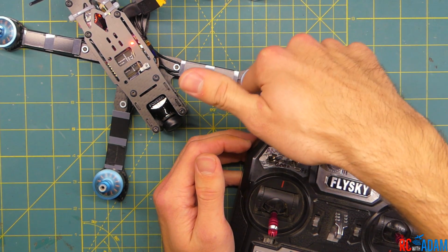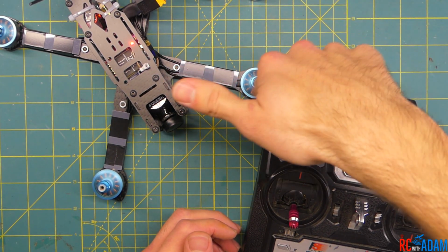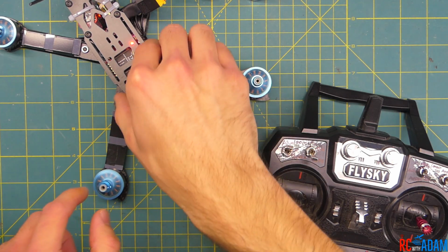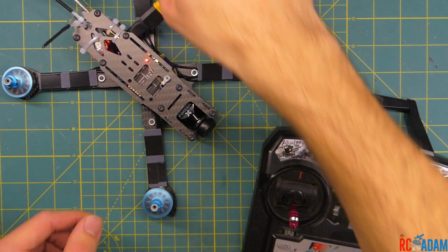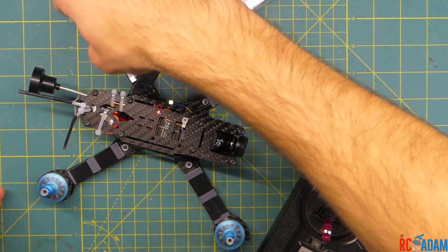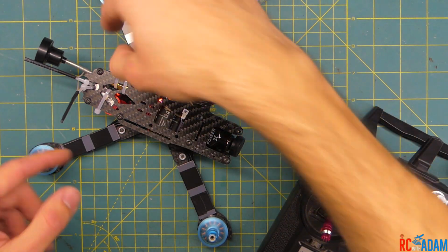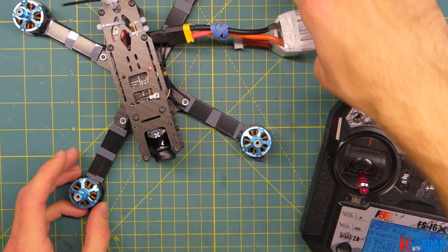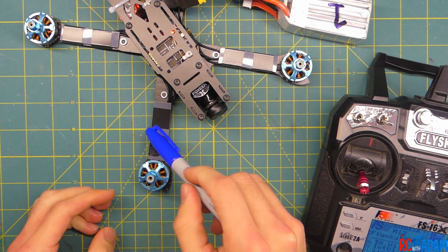Now what we want to do is check the motor direction. You can just put your finger around the motor and see which way it pulls your finger. Be careful. I can feel that this one is spinning in the proper direction. This one is not. That's spinning actually inward. This back left one is spinning in the proper direction, and this one is spinning the right way as well. So they're both spinning outward from the back middle. So we can disarm it now. We need to change this one. I'm just going to put a little dot to mark this one as the motor that we need to swap.